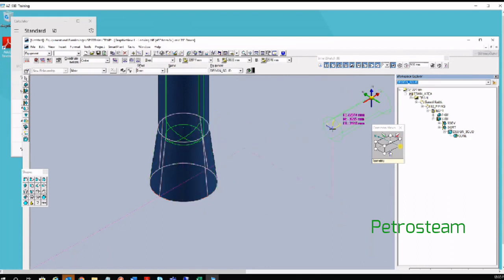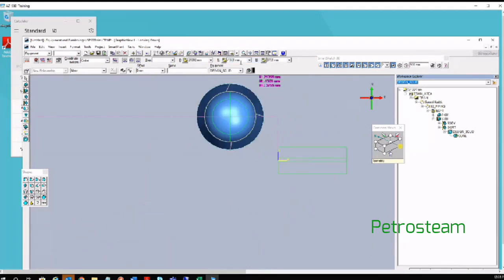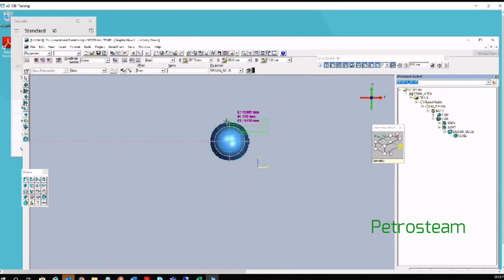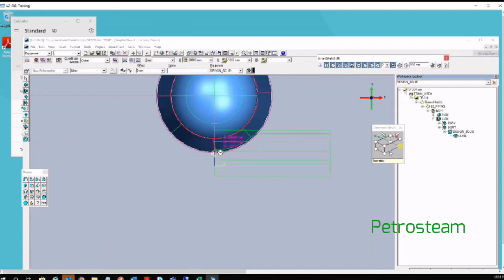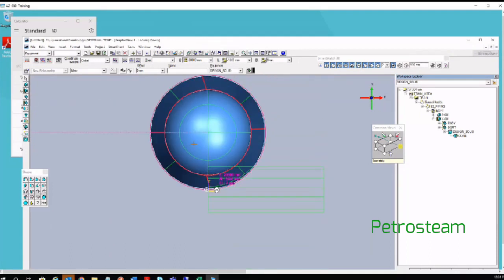So at this point, you are asked for the location again. In top view, the easting for this cylinder should be the same as the center of this, 20 meters. Okay, 20 meter. It has fixed the easting now. The northing for my cylinder should start from this place to this place. So this is 0 northing. It's 2 meter diameter, which means half of this is minus 1 meter. The northing should be minus 1 meter for me.